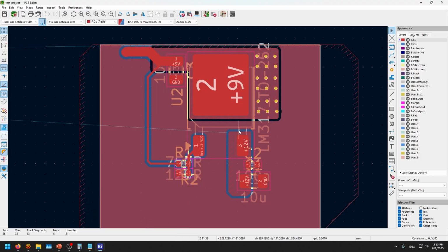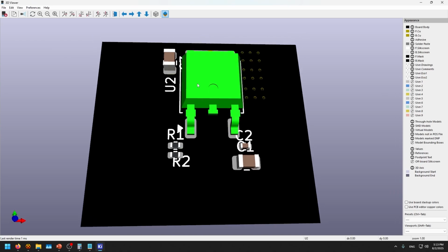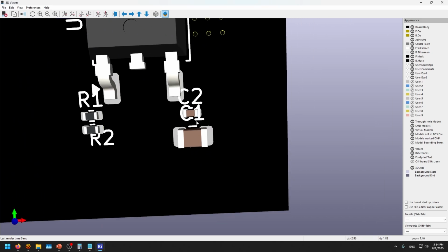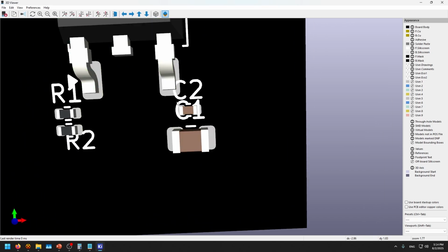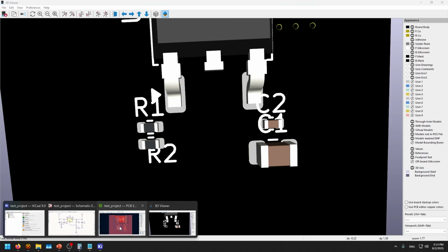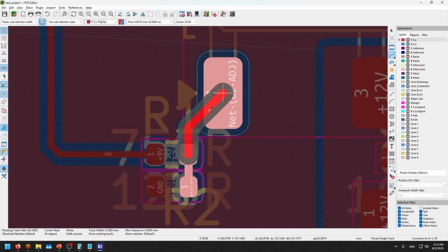Now if you go to the PCB design, this is going to be more clear. As you can see, I went with this package. This is the output capacitor. These are the two input capacitors. Look at how close they are to the pin. Basically, the silkscreen needs to be moved. And for the feedback resistors, it is important to lay them out extremely close to the feedback pin.